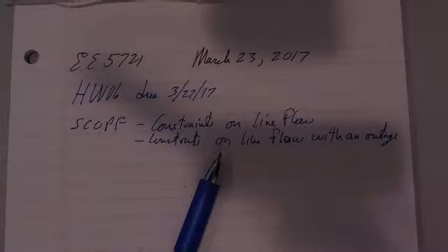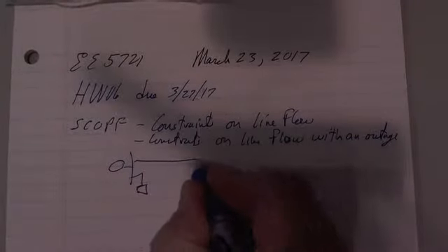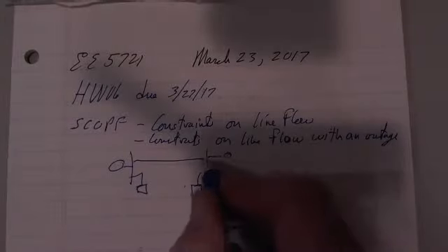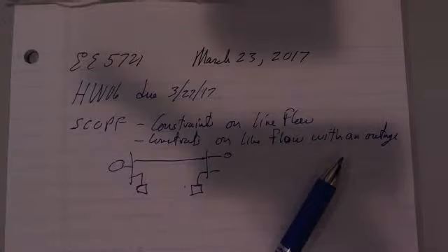So, and this results, we will see later on, this results in LMPs. And you remember my favorite little two-bus problem, where you had a load here, and you had a line, and you had a generator. Let me put the loads over here. And you remember that when the line flow was limiting, the solution to the auction required that the LMP, the price at each bus, was different.